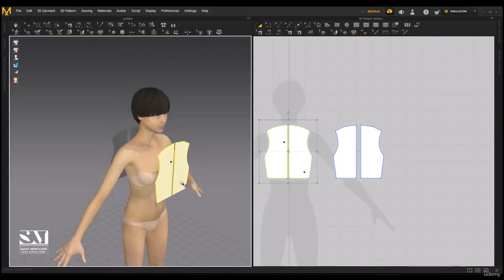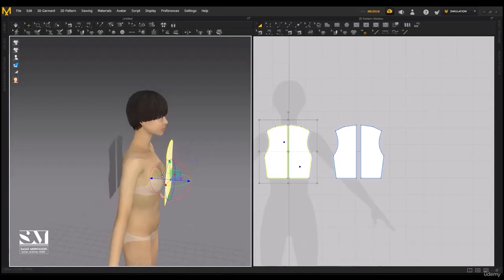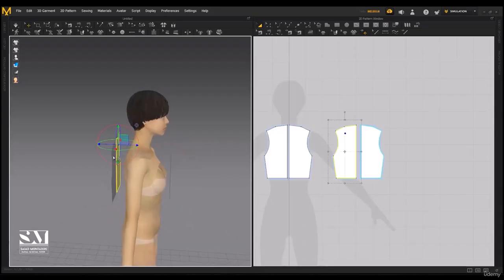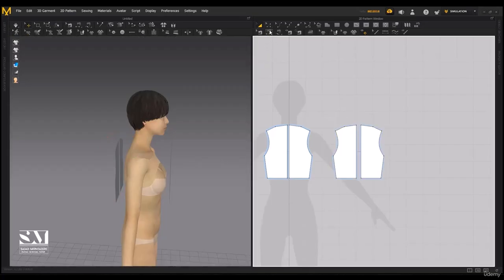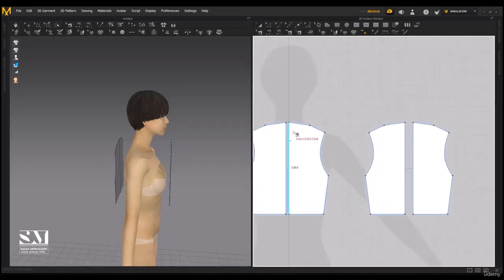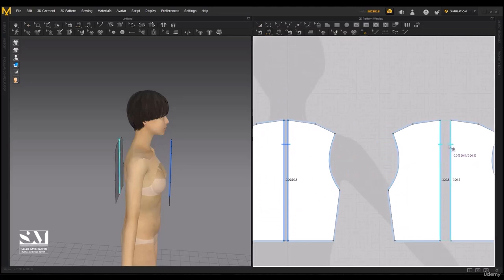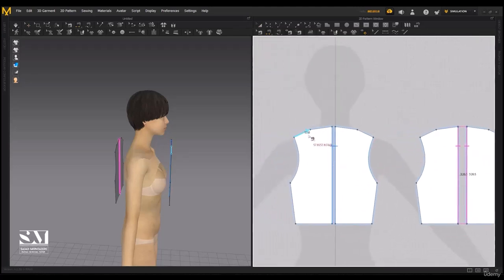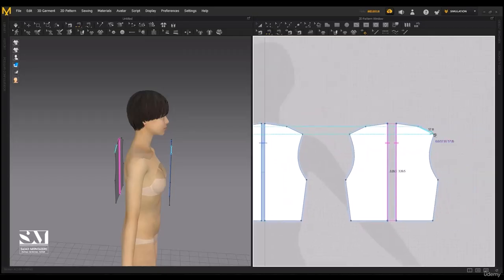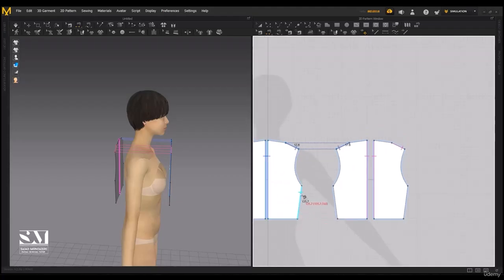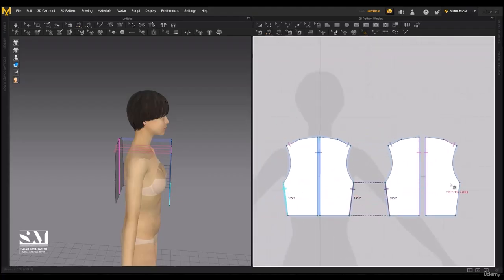And next, we can do the sewing using the segment sewing tool. I connect the front parts together, then the back parts like this. I can also connect this part to its corresponding part here, and this one as well, maybe. So here, this one as well, I can connect it. So you need to be a little bit patient and focused. If you have trouble selecting, use the blue points. And for example, this one to this one. Very good. And this side to that side.